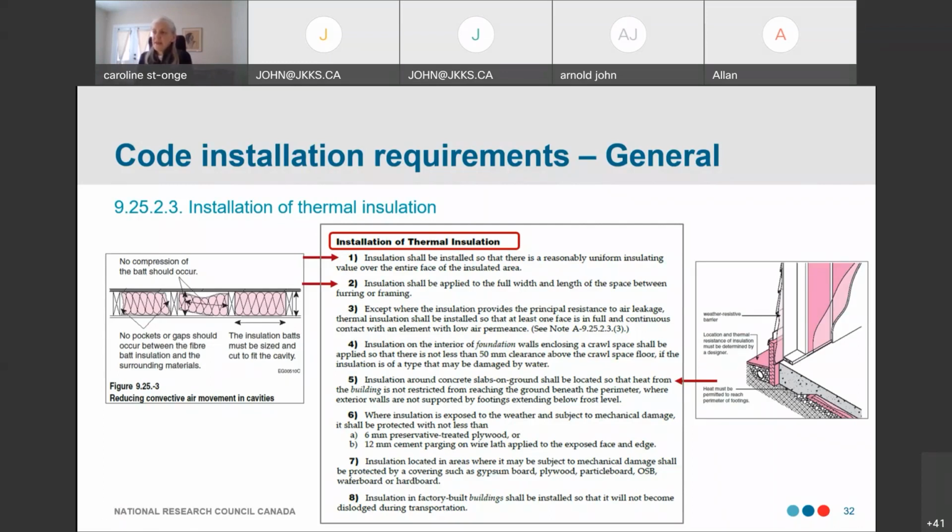So it's the same thing if you're renovating an old house and there is, let's say, foundation and footing, but you don't know the depth of the footing. Make sure you know first the depth of the footing to see if it is below the frost level prior to starting to insulate, because insulation, as you know, will reduce the heat flow reaching that area.